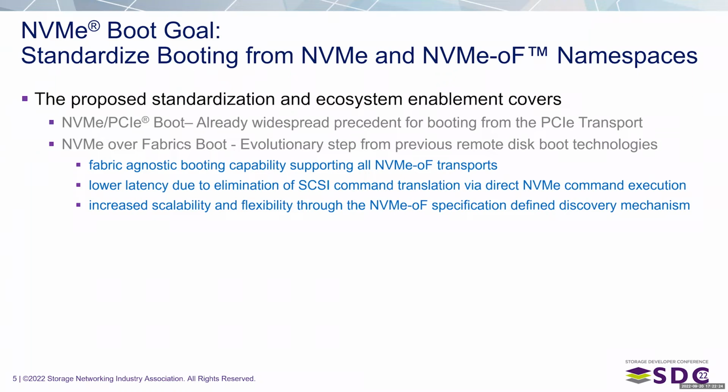The goal of this new boot specification is to standardize booting from NVMe and NVMe over Fabrics namespaces. NVMe is in fact already widespread for booting on the PCIe transport. What's new is, of course, over Fabrics boot, and it is different from other remote disk boot technologies because it is fabric agnostic, like the NVMe over Fabrics standard is.